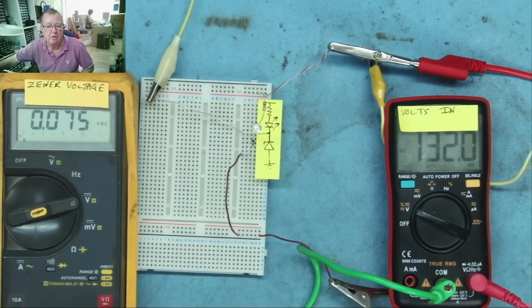Well, we don't have much at the moment. And see what's happening now. The voltage on the input is increasing, but the voltage on the Zener is not. And it won't until I reach the point where the diode junction in the LED is overcome. So at about 1.7 volts, 1.8 volts, 1.9 volts, that LED is now conducting in the forwards direction. And the voltage we see between the 2 meters, 0.6 on the left hand side, 2.5 on the right hand side, is a voltage drop across the LED.